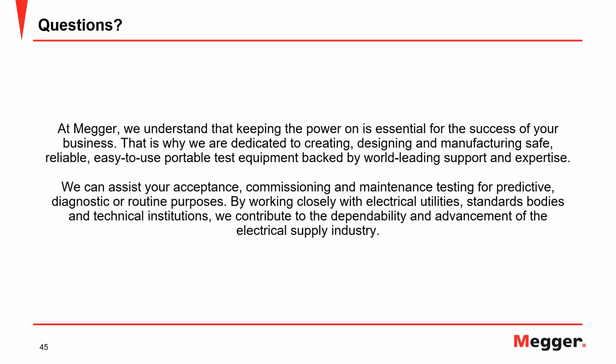That's okay. So if you have a single-phase transformer and you have one unique type of bushing mounted on this transformer, of course, you might not be able to do a comparative analysis with similar bushings on the same transformer, but the question would be, don't you have another sister transformer with a similar bushing to look at?